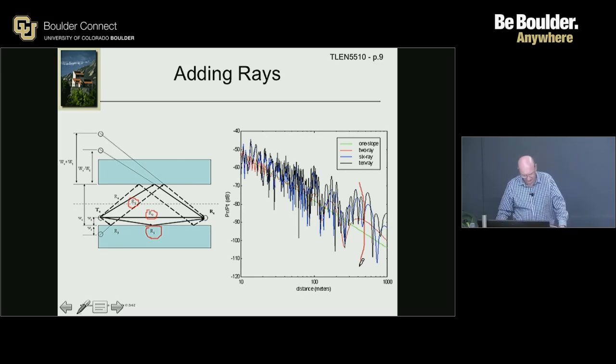The only other thing I want to mention is how to calculate those. It's explained in the notes a little better, but this is using the Pythagorean theorem in space now. Think again about what we did earlier for R0. In the vertical plane between Tx and Rx, we used the Pythagorean theorem to calculate L0 and L0 prime.